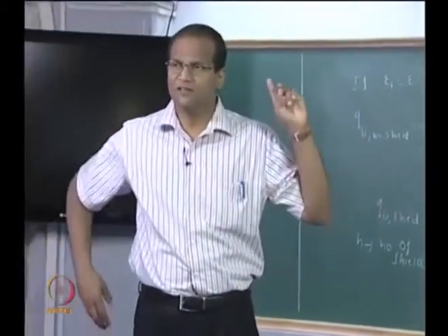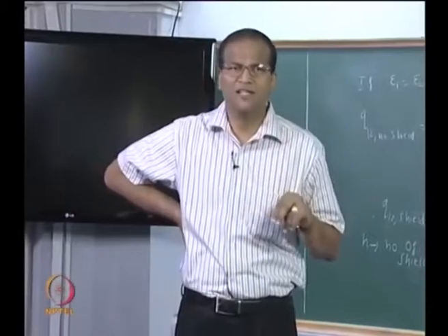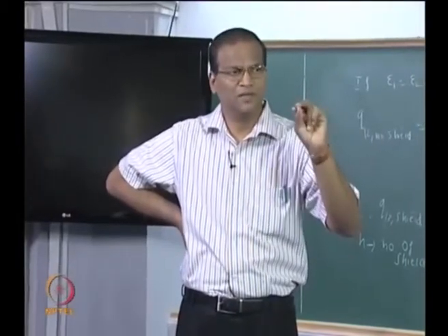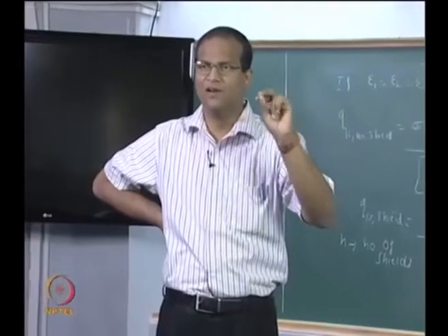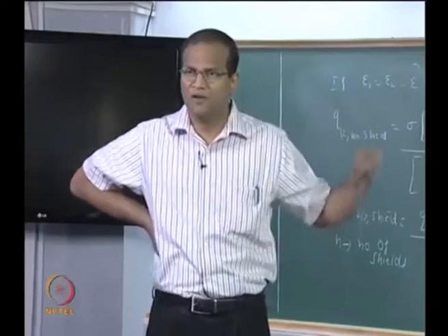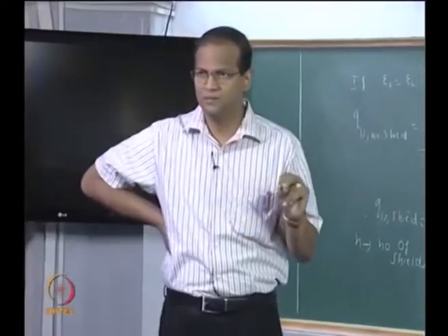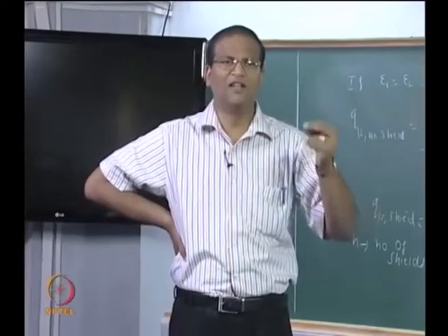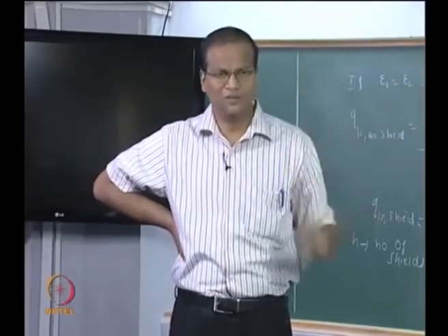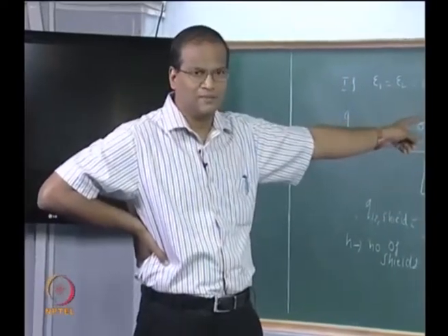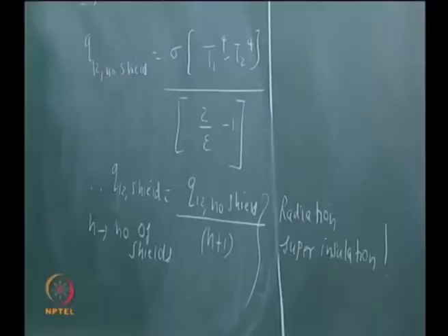While the heat transfer rate is straightforward, suppose for some reason I want to know whether this radiation shield I have introduced can withstand some particular temperature. It is imperative on my part to evaluate the T3. The T3 has to be evaluated as a post process quantity and see whether that T3 is okay for this material. Without the T3 we got this result. So, now as a post processing step you will have to evaluate the T3.